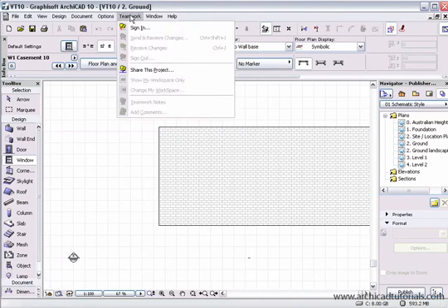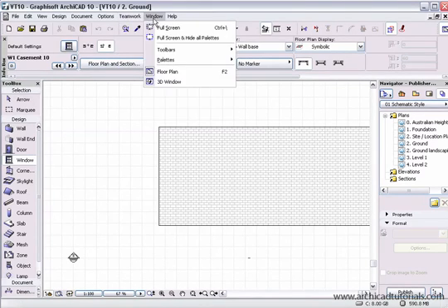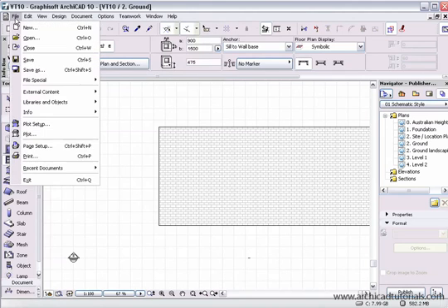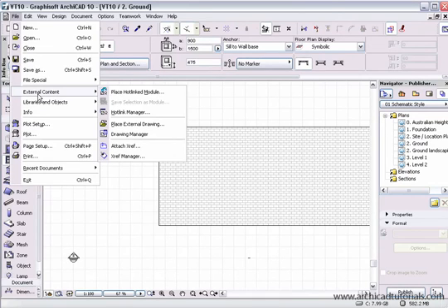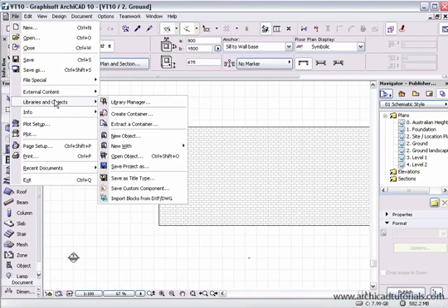we're working in. The Teamwork drop-down allows us to sign into and share projects, as it suggests, and under Window we can change the way we look at the program on the screen. Under the File menu, we have all the usual commands you're probably used to, the print, save and plot, but we also have access to external files such as hotlink modules, which is another ArchiCAD file, xrefs, and other files that we might like to use within the context of ArchiCAD, and also library objects.